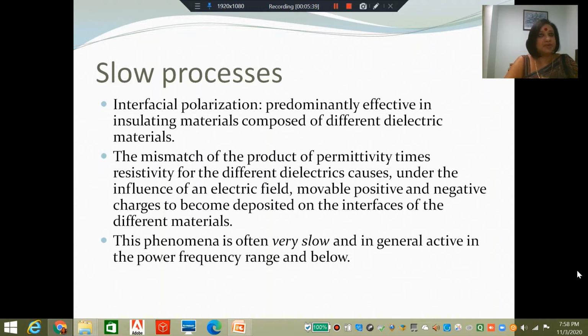So basically there will be a mismatch between J1 coming in and J2 going out, which means Kirchhoff's current law will no longer hold. You will not have divergence J equal to 0. You will have divergence J equal to minus del rho del t, which means that there will be a divergence of the current density at a point on the interface, and that will be proportional to the rate of change of charge accumulation.